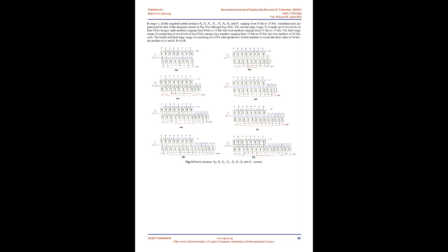For the purpose of high-speed operation of addition, the use of a carry propagation adder, CPA, 19 is needed. The CPA adds two binary numbers of 16 bits and produces an arithmetic sum, depicted in Fig 11b. The carries generated in successive digits are propagated from the LSB end toward the MSB end. The CPA can be created either by using ripple carry propagation or the carry look-ahead technique. Here we have adopted the first case, i.e., ripple carry propagation. A figure of a CPA, an example of its calculation and the symbol of CPA are given in Fig. 11 A, B, and C, respectively.